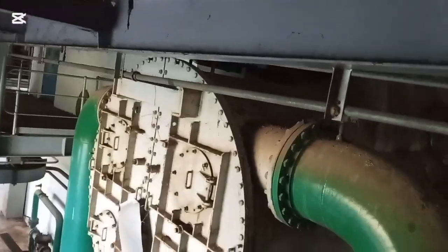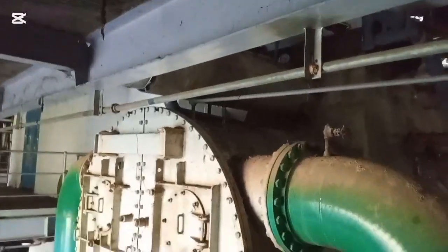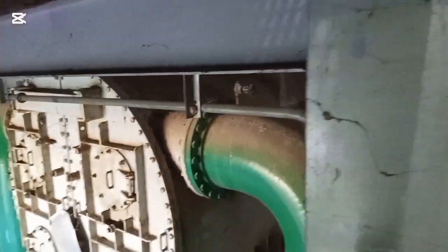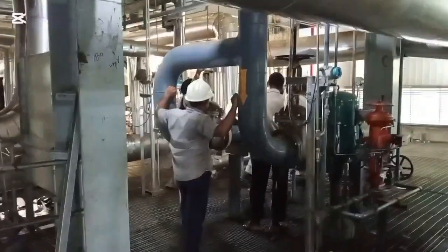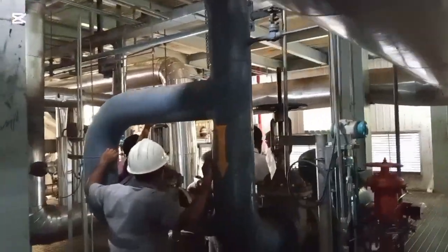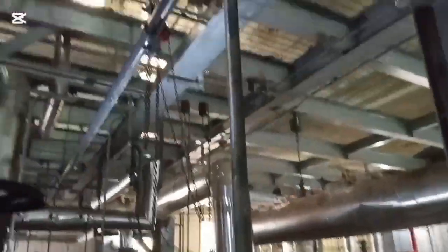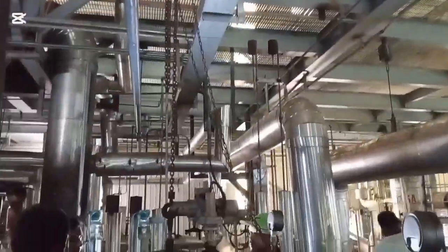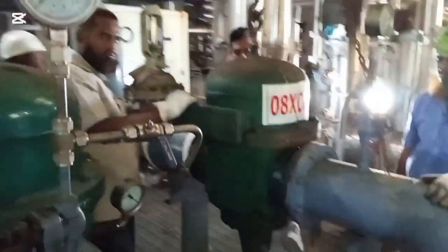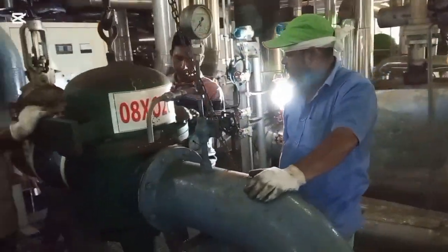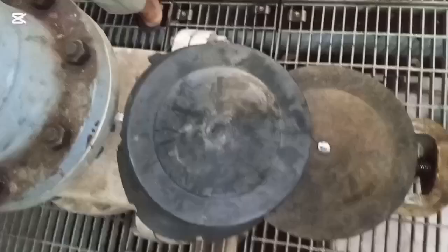An ejector is a device used to suck the gas or vapor from the desired vessel or system. An ejector is similar to a vacuum pump or compressor. The major difference between the ejector and the vacuum pump or compressor is that it has no moving parts, hence it is relatively low cost, easy to operate and maintenance free equipment.